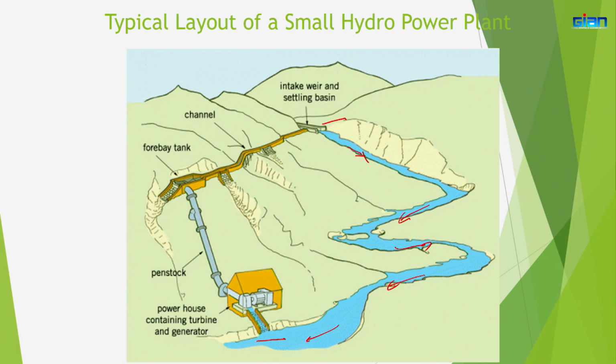So, here we have identified the height, and we have identified the location where the water can be diverted. Here we have identified the location for the powerhouse. So, there are a number of choices. You can put a penstock, a steel pipe, straight from here to here. Somebody might argue, okay, why not? They can do that, but that is not the way that we do it. We will explain why it is so. We normally take water through a low pressure canal or channel to a convenient location closer to the powerhouse.